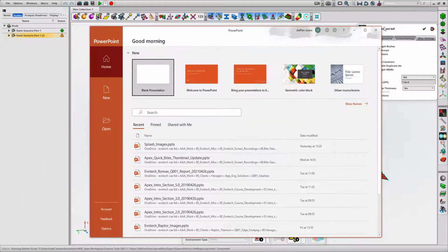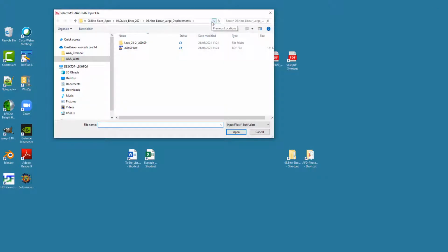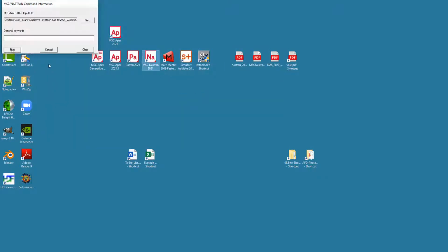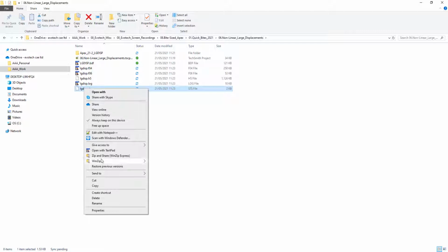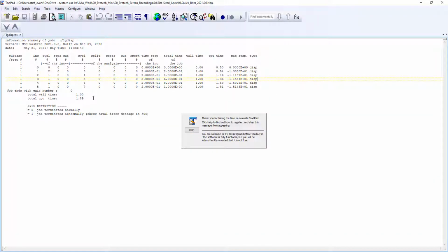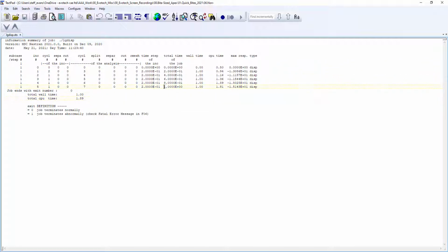Okay, so go into Nastran, run the Nastran job, LGDisp. So as we're running, we can see the generated files, so the status file we can open up, and we can see the incremental solve as it runs through to full load. We've got the job exiting with a 0 indicating it's terminated normally, or correctly rather.